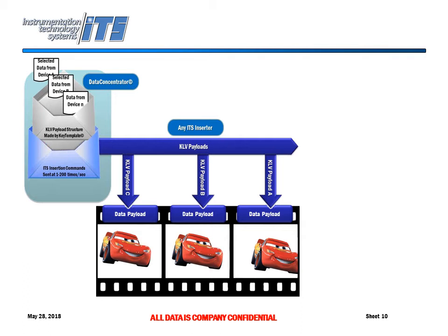There are different buffer lines at the bottom, so that actually changes the time from the top of the frame. So we always capture on the first line of the new frame that time and then insert it in line 9. Right after that, we'll put your payload packets that have been defined with the key template. And so as this data comes in asynchronously, on every vertical sync point, we capture the last full packet of payload and insert it into the metadata as a KLV packet defined by SMPTE. So each frame then will have unique data that's synchronized on its insertion time.